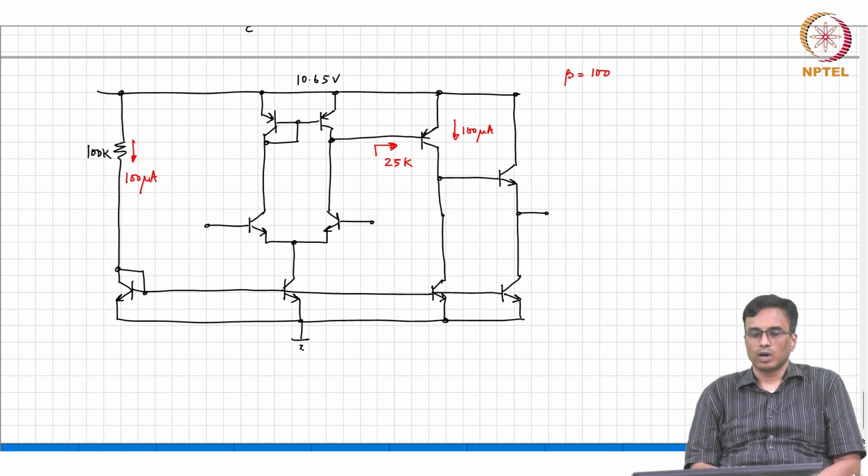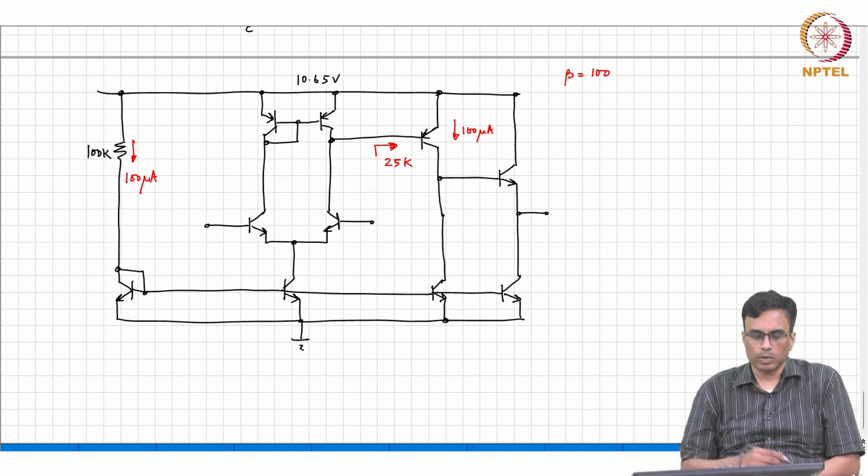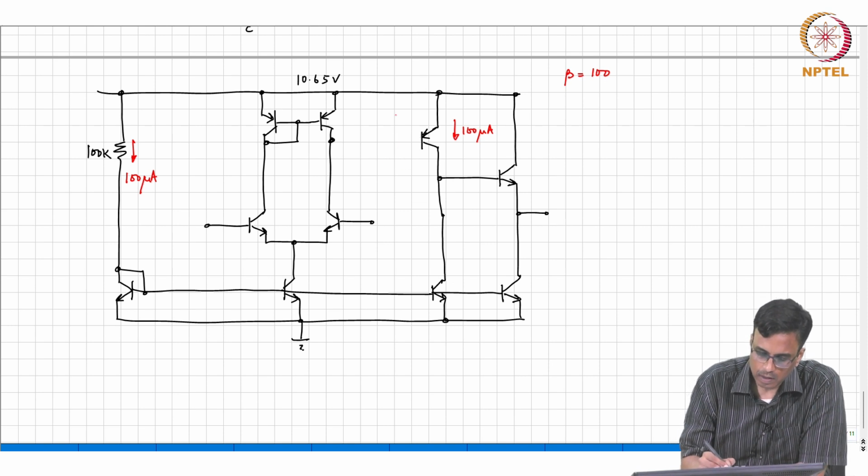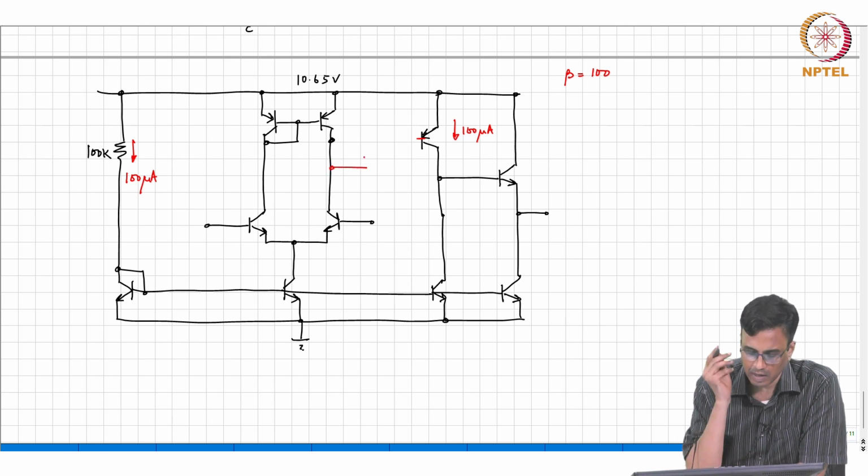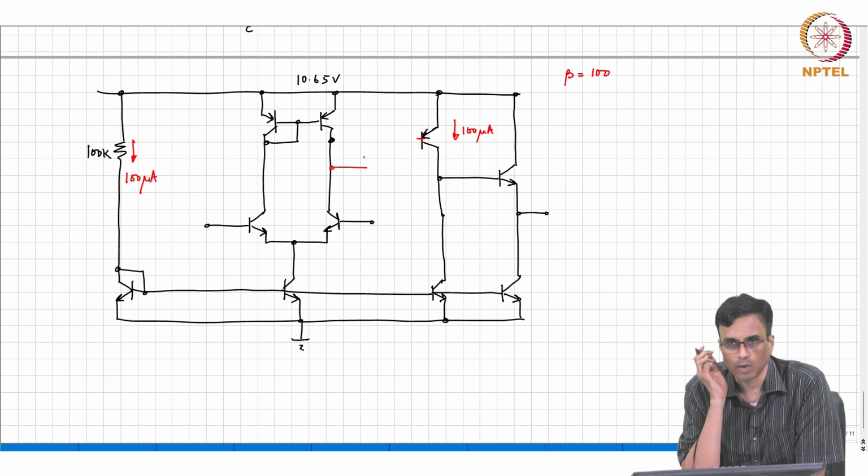gain. So, what do you suggest we can do? You want the input impedance to be higher, you want the same voltage, but the input impedance must be higher. So, what controlled source will you put between these two terminals? You want this voltage to come here, but you do not want any current to be drawn there. In principle you want to put a voltage controlled voltage source. What is the simplest voltage controlled voltage source that you know? Common collector. So, will you put an NPN common collector or PNP common collector?